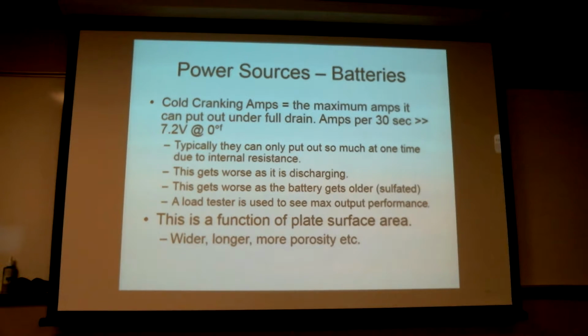So you actually drive that through the tar and catch either side of the cell, okay, and note it reads from 1 to 2.5, and there's a nice big heating element in there. You just dive that in there and this guy would start getting hot. 1, 2, 3, 4. And if it drops down below, they've got a little thing here that says dead, discharge, charge. So if it stays up, yep, that cell's okay, that cell's okay, that cell's okay. Oh, that one's not good. Let's heat that tar up, pull the tar off of there, pull all the lead out of there, flush everything out of that cell, and they'd fix that one cell.